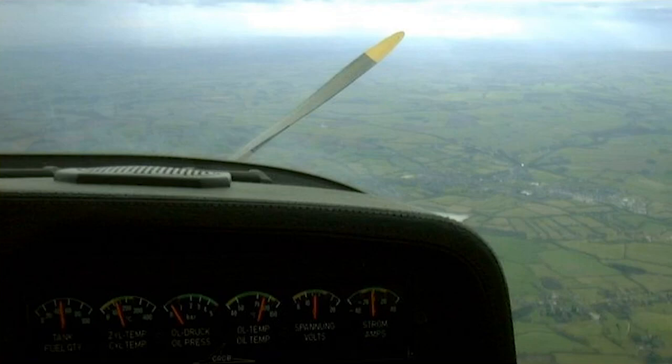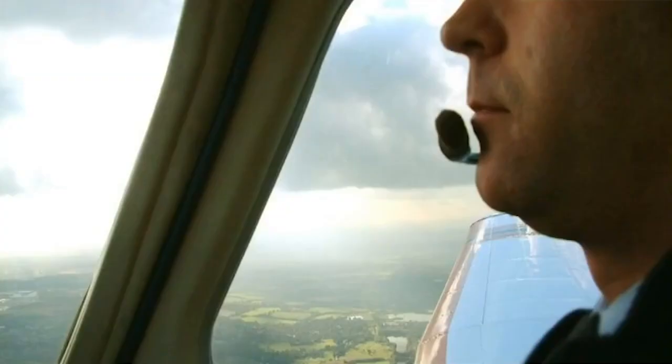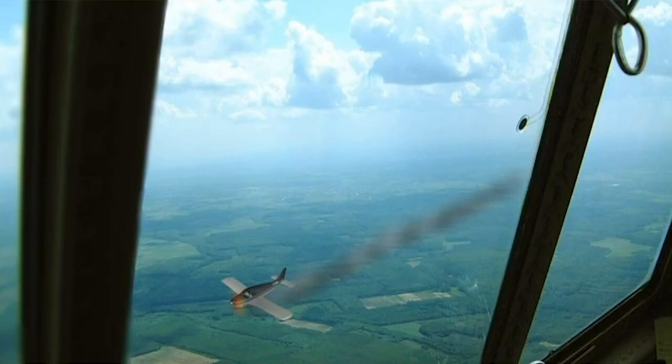If an aircraft experiences difficulties in flight, they can be divided broadly into two types: distress or urgency. The definition of distress is: the aircraft is in immediate and imminent danger and requires immediate assistance. In a light aircraft, the distress situation is most easily communicated to air traffic by an RT call prefixed by Mayday, Mayday, Mayday. The definition of urgency is: the aircraft has an urgent message to transmit concerning the safety of persons on board or within sight.